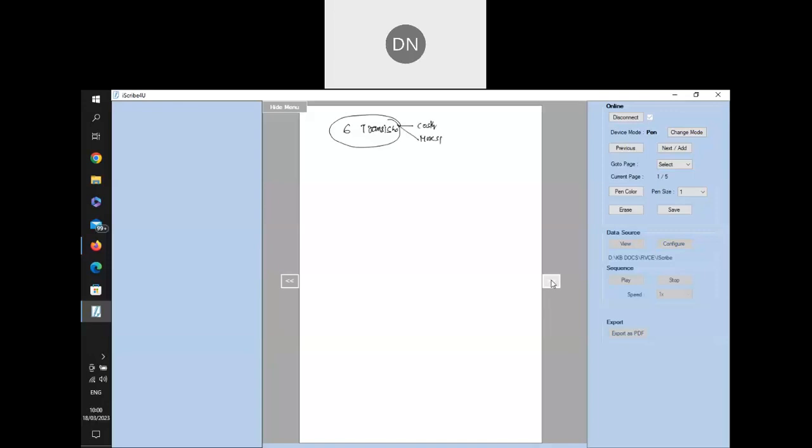That is why every one bit of SRAM is very costly and requires more space, because the space consumption is very high, as 6 transistors have to be accommodated. But one of the properties of CMOS, which has been used to design the circuit, is low power consumption. And since flip-flops or latches have been used for the technology, it's high speed.